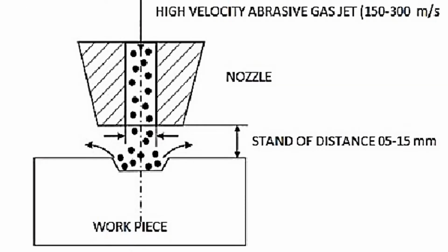This picture shows how machining can be done. When an abrasive particle impinges on the work surface at a high velocity, the impact causes a tiny brittle fracture, and the air or gas carries away the dislodged small workpiece particle. This process is more suitable when the work material is brittle or fragile.